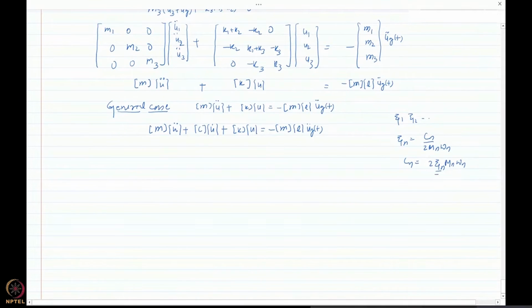And you need to formulate that, and we saw what the different methods were. There were mass proportional damping, stiffness proportional damping, and also Rayleigh damping, in which case we formulated it as a linear combination of mass and stiffness matrices. So in those cases, if the damping for one or two modes is given, we can find out damping for the other modes as well. If that is clear, let us write down the single degree of freedom equation corresponding to this equation.